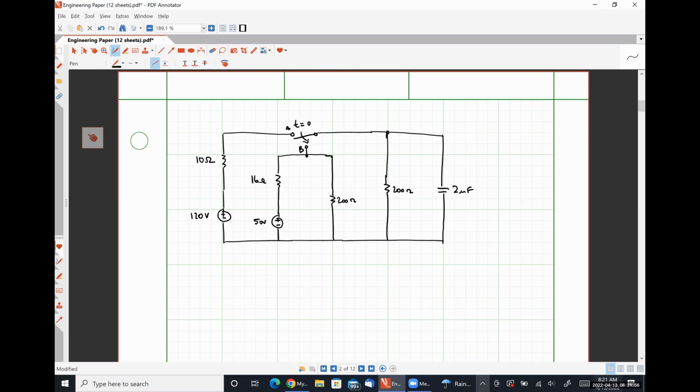So effectively, at t equals 0 minus, the 120 volt source in series with the 10 ohm resistor is connected. And at t equals 0 plus, abruptly, the 50 volt source in series with the 16 ohm resistor is getting connected instead. And we're going to see how the capacitor responds to this change. While we're at it, let's also determine this quantity IR of t.